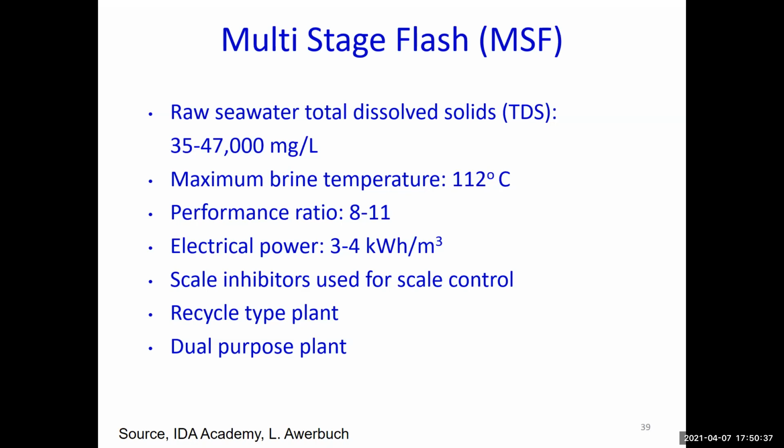which means that this can be done, but you have to guarantee good quality of intake water to have low power for the RO. If you are going to run into problems with the intake water, this value might increase and reach up to 8 kilowatt hour per cubic meter, as some of the engineers have been mentioning in some places that they have RO units and the kilowatt hour per cubic meter is quite high.